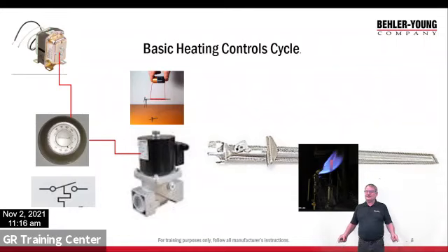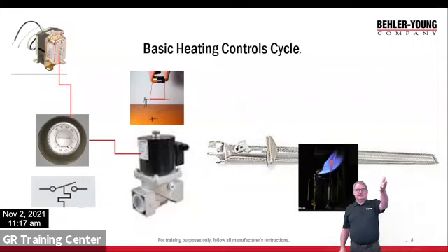Now, what's a thermostat? It's a switch. All the switch is a contact, right? So I take my 24 volts, the switch closes. Now my power can go to my electric magnet. In your picture there, the guy's holding the magnet on the battery. So it's like take one end away and touch it again. That's what the switch does. So the thermostat closes. We send 24 volts to the magnet. It pulls the valve open. Burner comes on and it lights. Hopefully, providing that the pilot's lit.